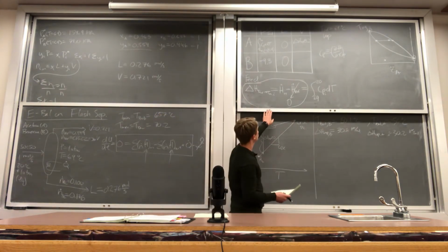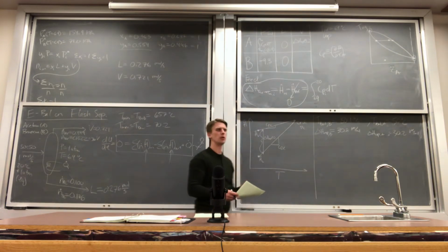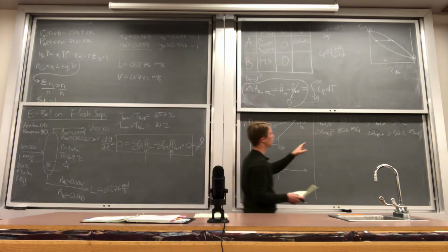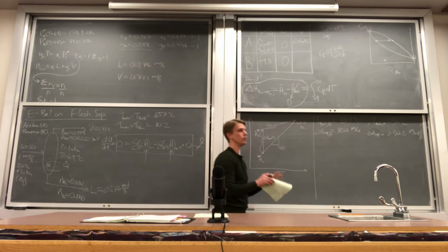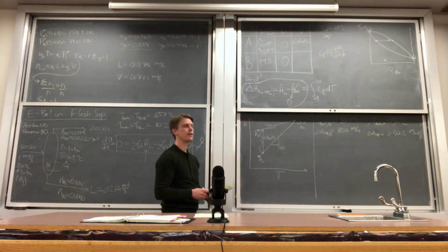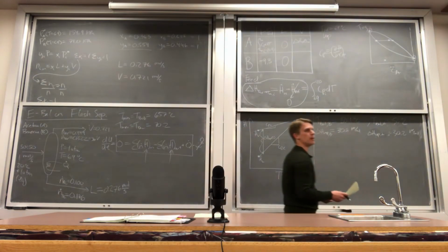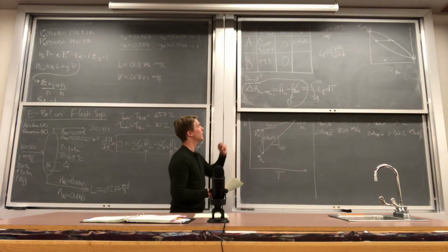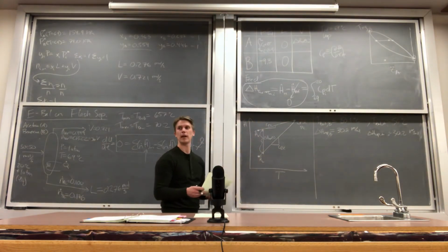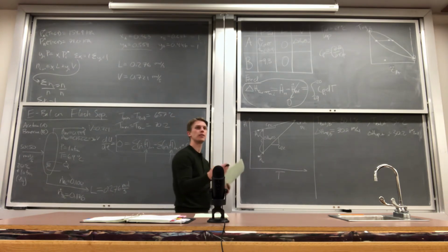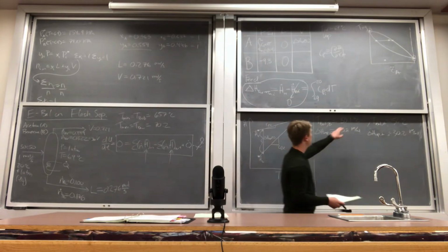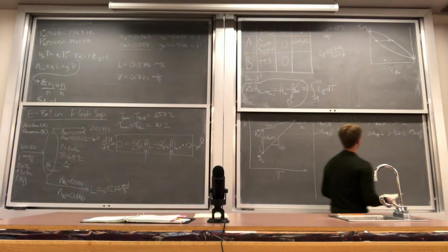Since we're at 1 atmosphere, we're relatively close to the normal boiling points, and so this process that we're going to show right now is not going to be so totally off from if you just neglected it and assumed these were constant. But I want the pathway to be more apparent, because if this was at a significantly higher pressure, you would be having to estimate the heat of vaporization at, let's say, 200 C, which is a lot different than going from 80 to 69 or 56 to 69.